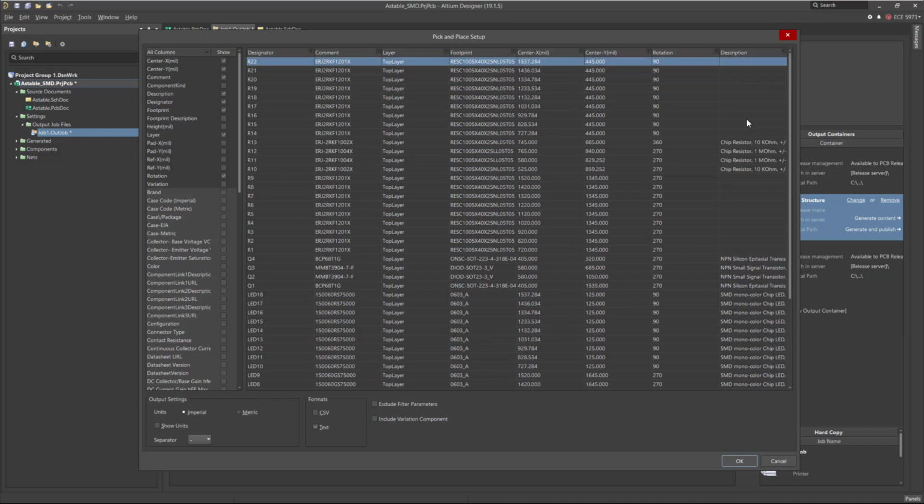Because of the polarity and pin number 1 for the integrated circuits, or the ICs, that's why you need the polarity. And here you can see the designator. So as you saw in session number 1, a pick and place machine or robot arm will pick up the component from the component rail and move it to the PCB in its position and place it on the solder paste before it goes into the reflow oven for soldering.